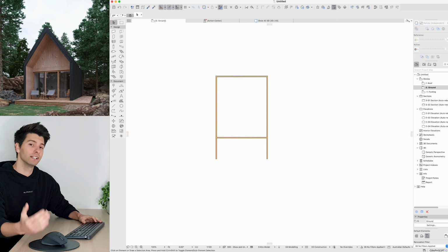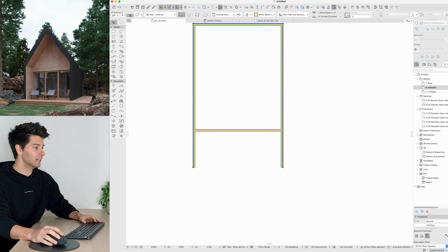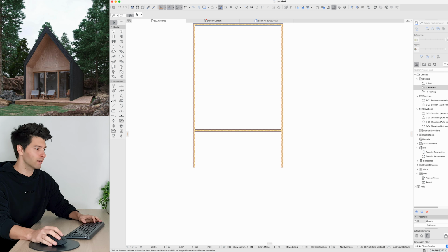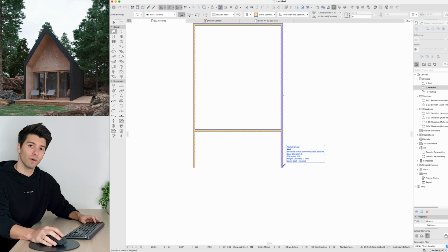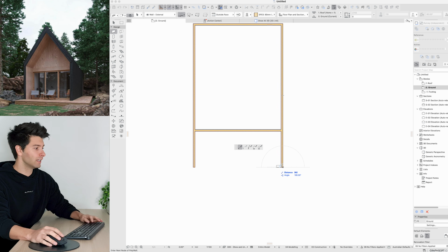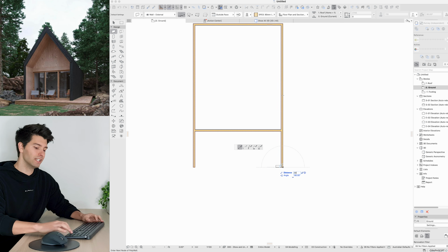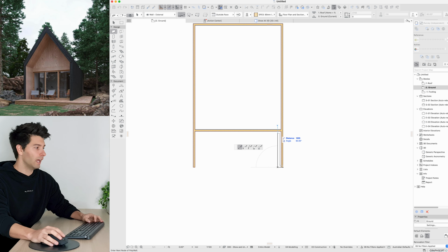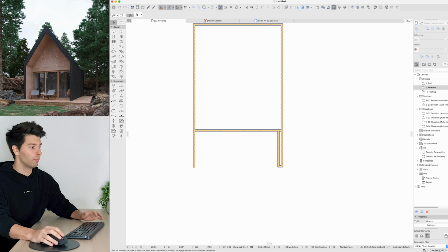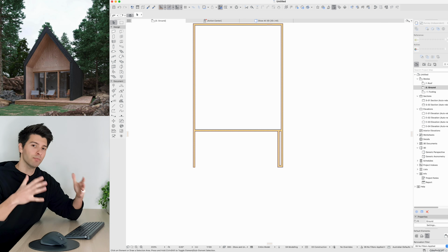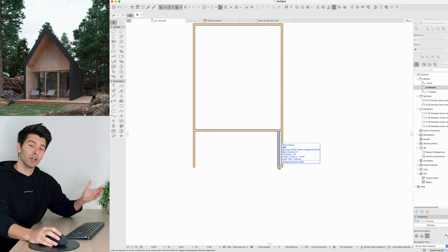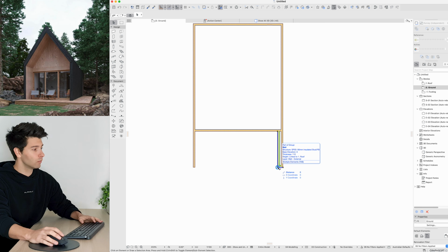to create exactly what we see here in this image. Now, more than likely what is happening is this wall here is not just one 90mm stud partition. So once again, we're gonna hold our option button, click once across. I'm gonna tap D for David, type in 300 and double click at the top to basically return and bulk out our wall frame.